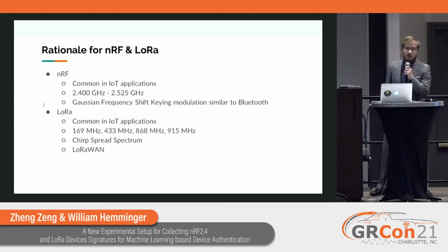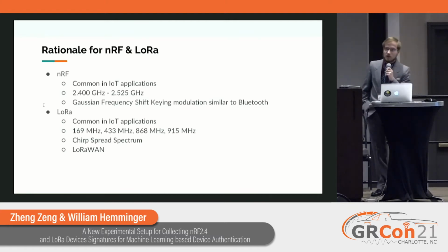Whereas LoRa, on the other hand, is most commonly seen in large-scale monitoring applications, like relaying soil moisture content data to a farm, or tracking the strain on a distributed power grid, or making buildings smarter to improve energy efficiency. And LoRa is ideal for these kinds of situations because of its capacity for long-range transmission. This is because the LoRa modulation is a subset of chirp spread spectrum modulation, where the frequency varies linearly over time. And this makes it very easy to decode even over long distances.